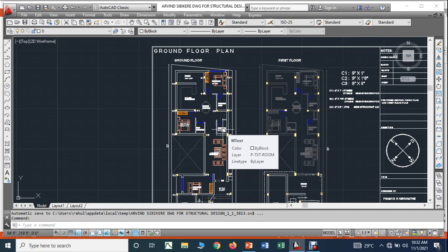Therefore, usually what the engineers will do, even though it is like that, they will continue the column in the middle floor also. Okay, so again, if you go to the next floor, and the architect wants that same plan which is there in the first floor, again you cannot start the column. That becomes the floating column. So the floating column is just for the architecture purpose. It will not carry any loads. Okay, when I take up the second problem, we will understand what we mean by floating columns.